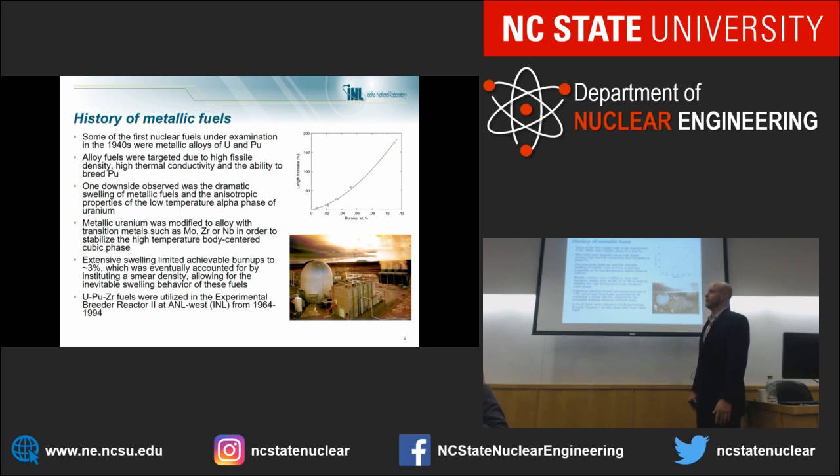One of the big issues is that these things swell like crazy. This is from a very old study showing a length increase as a function of burnup for alpha uranium, where we're showing, yes, that is a 200% increase in size. These things really, really swell with 10% burnup. So that's untenable in a reactor.